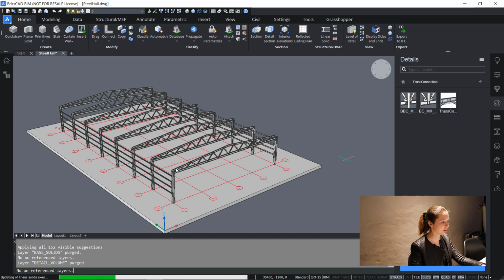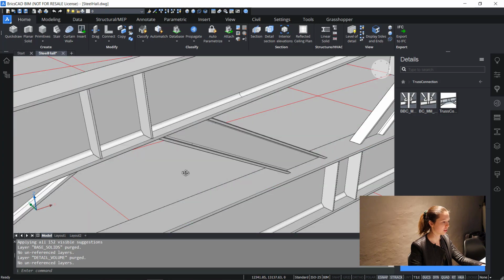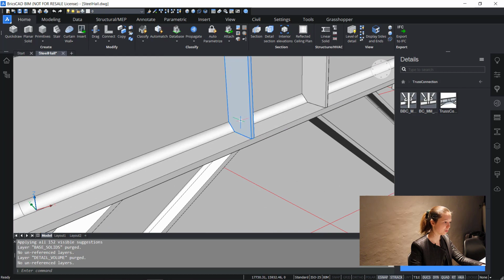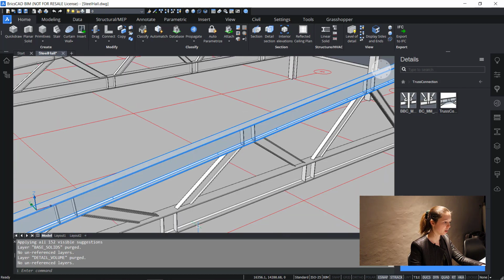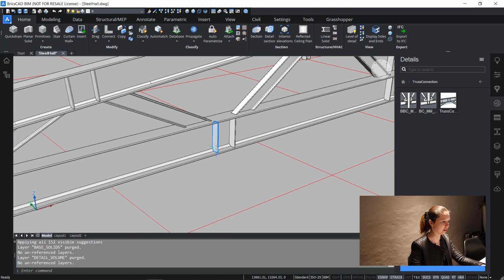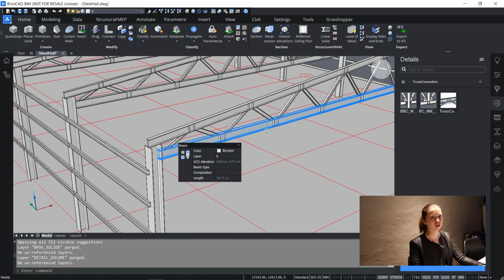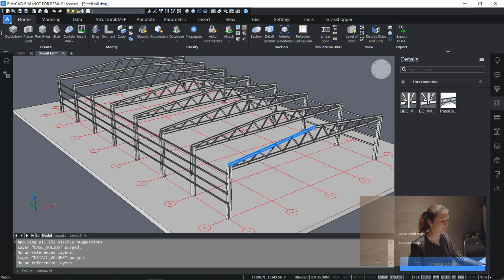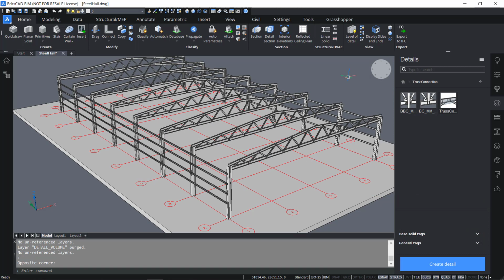So you can see now that it's done with the morphing of the geometry, and it was updating the linear axis. And if I zoom in, you see that now the connections are nicely modeled. Even the plates adapt themselves to the profile, because one profile was bigger than the other, and still the plates adapt themselves. So that's pretty convenient that you can use Propagate on a parameterized detail. In the next step, we will make a detail for the details panels ourselves.